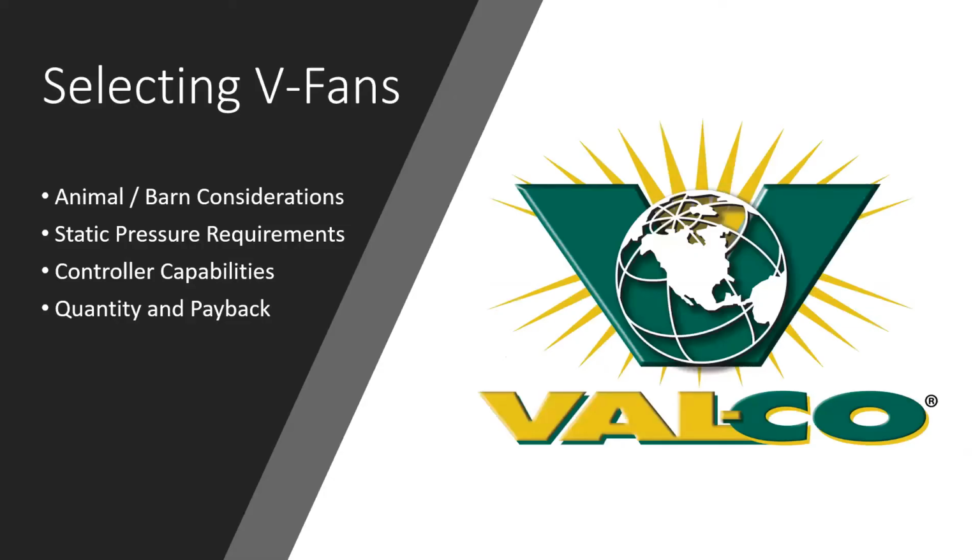So some of the criteria that we need to evaluate to select the proper fans are animal barn considerations. Stocking density has a huge impact, based on the difference in minimum ventilation rates, on how many fans you would have linked to that min vent stage.